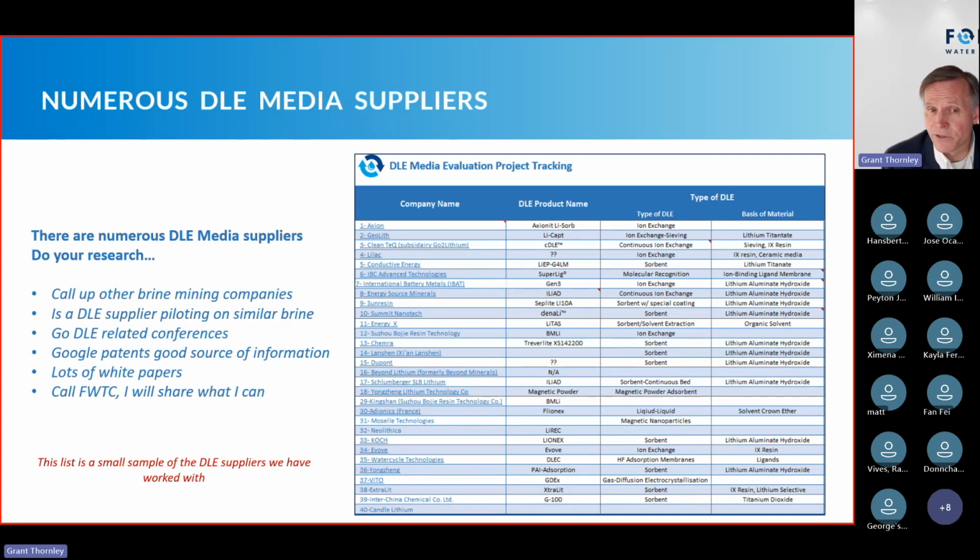Another thing I found very useful: a lot of the time the DLE media providers will say, hey, this is proprietary technology, I can't share that with you. If they do say that, I still really want to understand what the resin is and how the media has been constructed, because I can deduce the pitfalls or potential weaknesses of that media by understanding the formulation or the actual structure.